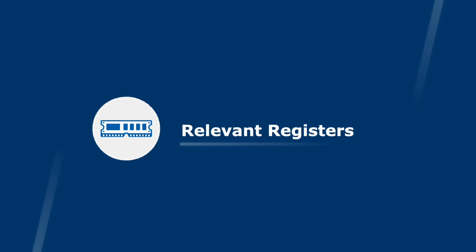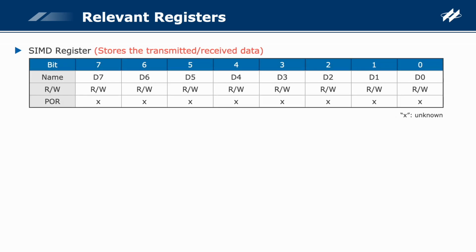Introduction to relevant registers. As the serial interface module of the HT66F3195 has integrated the SPI and I2C interfaces, and the SIM relevant registers contain the functional settings for both interfaces. The first register is SIMD, which is used to store the transmitted or received data.